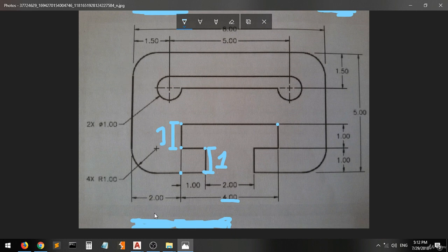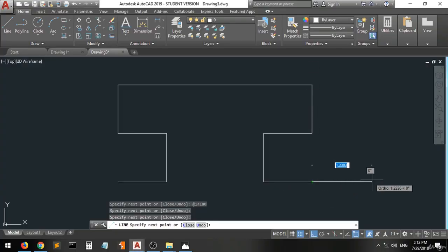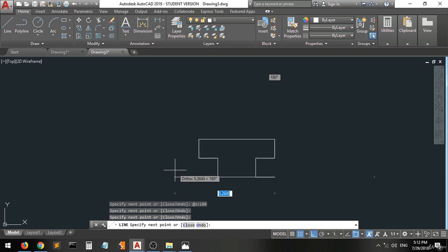Okay, and we will use the fillet command to create this shape. So we'll move from this distance here to here of a distance of 2, and this will be the same. We'll move from here to this thing here, and it will be a distance as this. Okay, do it together. So we'll zoom back a little bit. We'll do at 2 in the direction of 0.